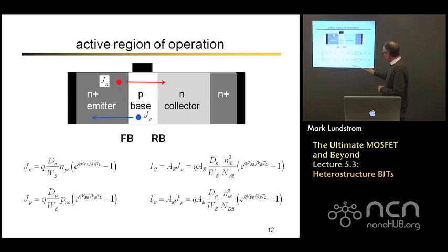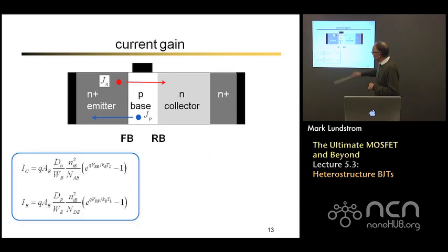And we can write then the base current with this expression, and the equilibrium hole density is just Ni squared in the emitter divided by the doping in the emitter. So we get those two simple expressions. We're ignoring things like recombination in the base, which if we have a good transistor is not a very important factor. And these are simple, but they're really very good descriptions of what goes on in a decently operating transistor. So we have these two expressions, collector current, base current.